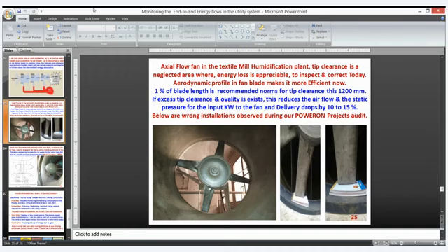And another thing is, if you see the blades of all the axial flow fans, aerodynamic profile has become mandatory. It needs to be implemented. We are all using the gravity die-casted fans, but that is the past. In recent years, we go for an aerodynamic profile that definitely improves the fan efficiency by almost 15 to 20%. So from 40% of an axial flow fan, you can almost bring it to 70% efficiency of the axial flow fan system.